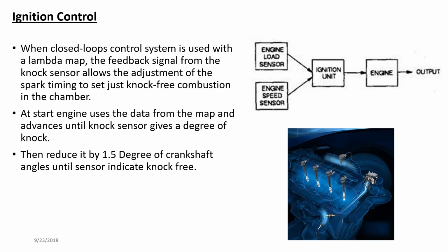For example, if the knocking started at the third cylinder, it's possible to take corrective measures on the fourth cylinder, because the signal is coming separately. You don't have to wait for some time to make this work again.